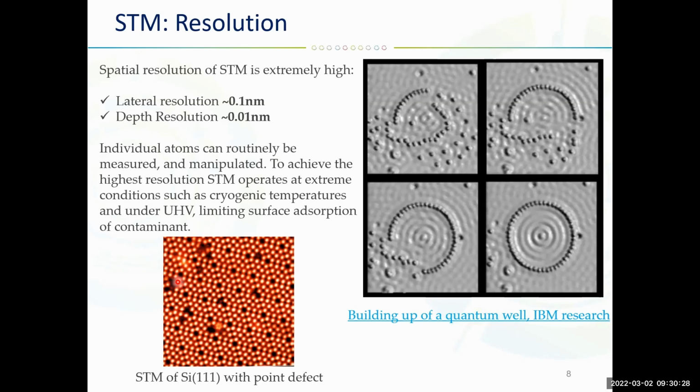These defects can occur in general for three main reasons. First of all, it is impossible to obtain any substance in 100% pure form. Some impurities will always be present. Even in an ideal world, if a substance is 100% pure, forming a perfect crystal would require cooling the liquid phase infinitely slowly, which would allow all atoms, ions, or molecules to find their proper positions. We cannot cool the sample that slowly. Cooling at more realistic rates usually results in one or more components being trapped in the wrong place in the lattice, or in areas where two lattices that grew separately intersect.